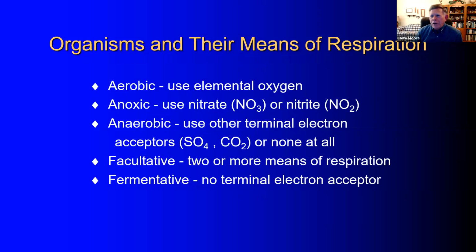Being a former professor, I love to talk about biokinetics and facultative heterotrophs and autotrophs and all this stuff. But again, what we've got to realize is that the BOD load that comes into the treatment plant gets channeled in 2 directions. Some of that BOD load is going to be channeled into growth reactions or synthesis reactions. We're going to grow biomass, and the other part of that BOD load is going to be channeled into energy or oxidation reactions. And we as design engineers, and you as the operator, are going to control how that incoming organic load is channeled.